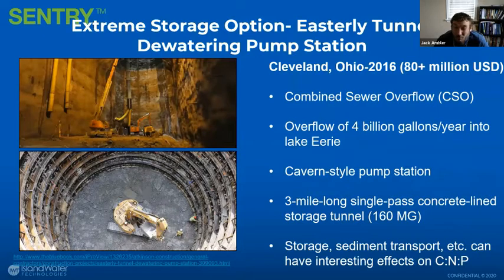It was an $80 million project. But basically what they were dealing with was their plant and their collection system were not able to handle about 4 billion gallons per year, which were flowing directly into Lake Erie. So they built this cavern style pump station. It's about a 160 million gallon volume to hold in a 3-mile long single pass concrete lined storage channel.